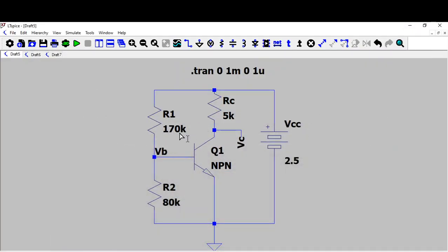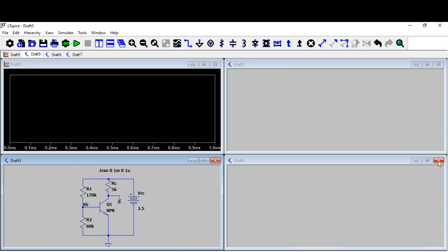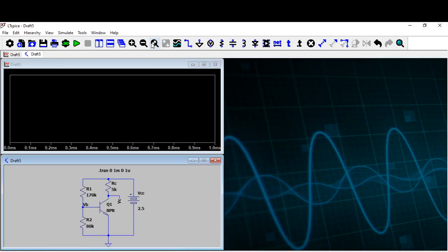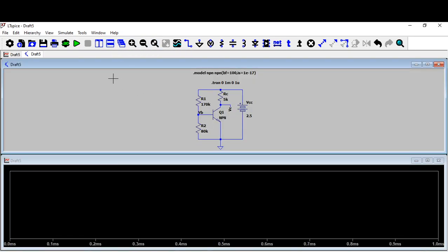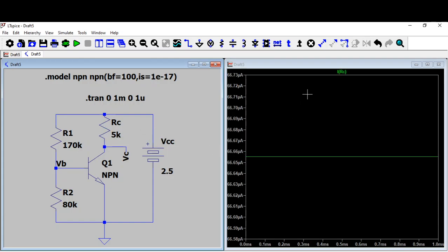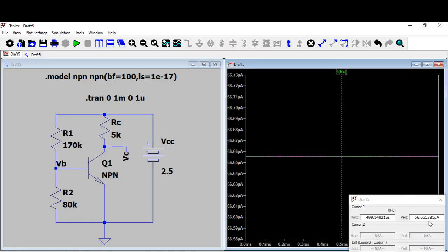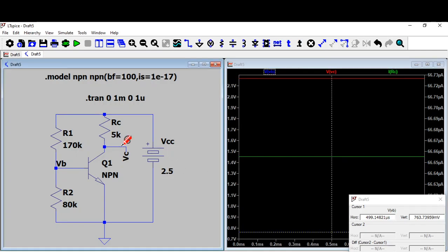If I run it, now this is my IC, which is 66.6 microampere. This is VBE, which is 763, and the value of VC is 2 point...